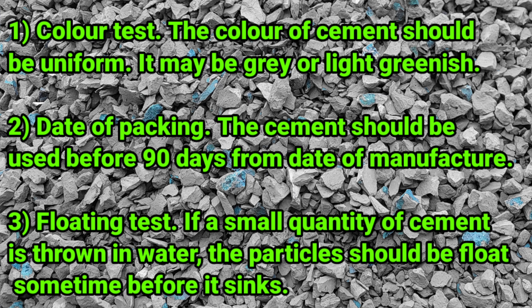Number 2, date of packing. The cement should be used before 90 days from the date of manufacture. Number 3, floating test. If a small quantity of cement is thrown in water, the particles should float for some time before it sinks.